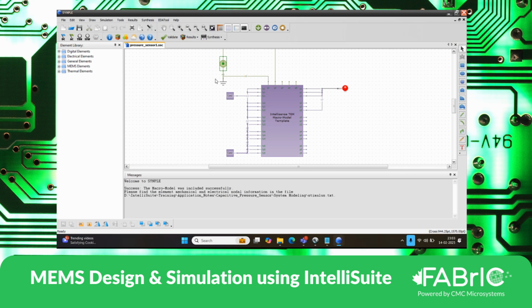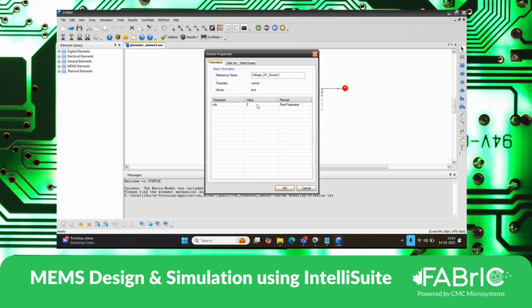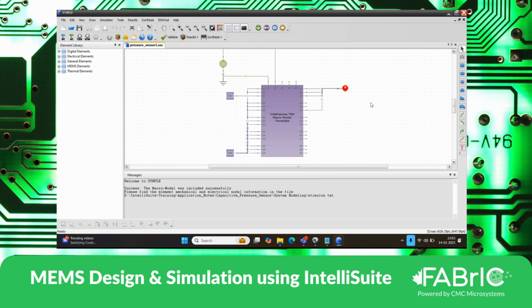For that, I connect a DC 5 volts just to run the simulation. I can perform DC simulation, that is static analysis. AC simulation is frequency analysis. TRN, transient, is dynamic analysis.